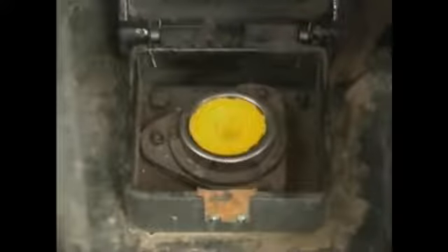The machine should be leveled to within 1% of grade. One way to check a crane's level is to place a bubble level on the superstructure near the rotating mechanism or turntable. Another way is to check the crane's level gauge if it's equipped with one.